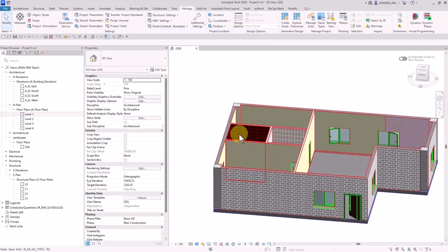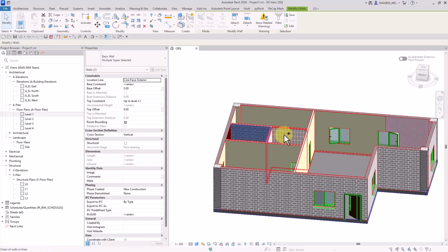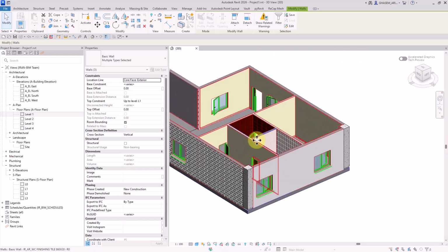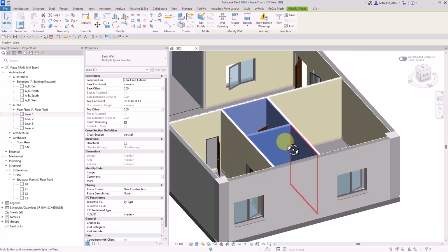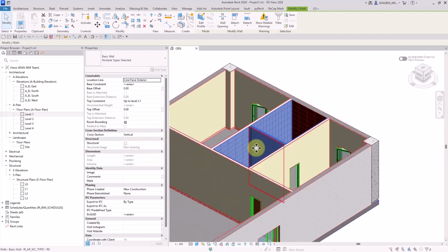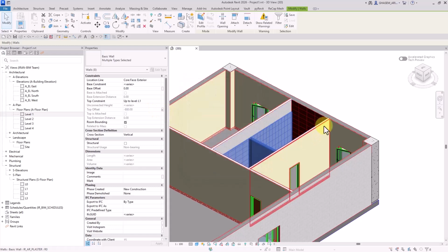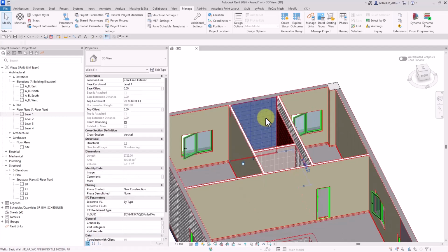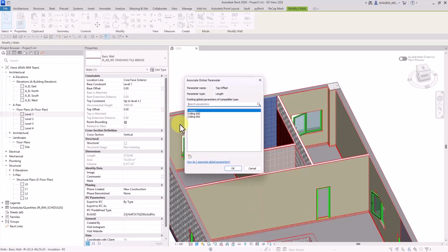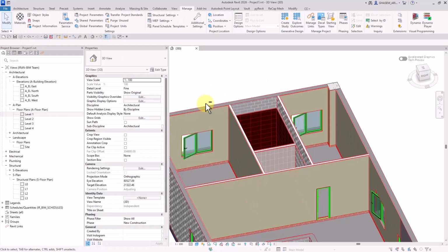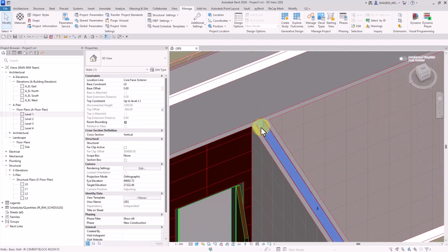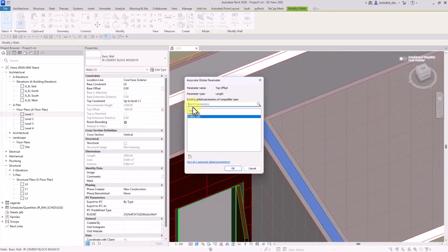Alright, now I'm going to go ahead and try selecting these areas. Okay. And then set their top offset on ceiling -800. As you can see, I don't really need to specify anything manually. Okay, this wall is a framework, so I'll set this on none.